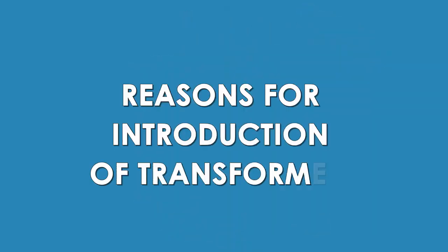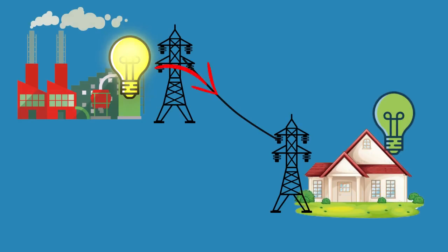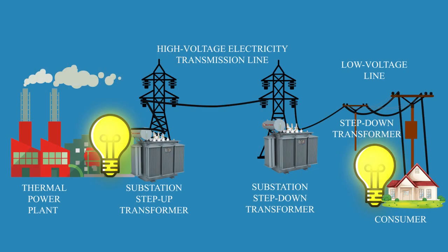Reasons for introduction of transformers. The need for transformers arose due to the losses that occurred during electricity transmission over long distances from the locations of electricity generation to the locations of its consumption. Reducing these losses requires increasing the voltage. The longer the transmission line and the greater the transmitted electrical power, the higher the voltage should be.